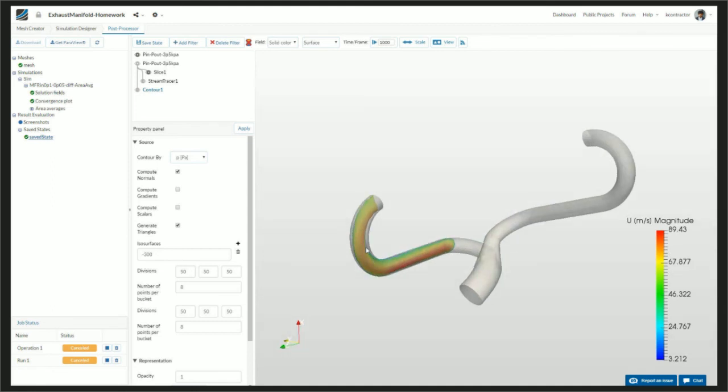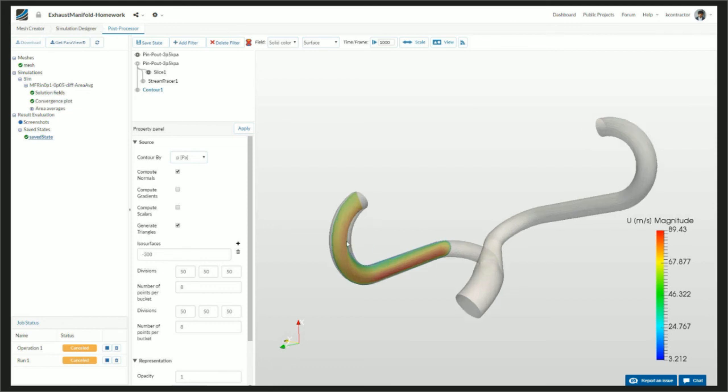Then again, it separates here in this region. The green region is where there's a separation zone, and this is what leads to some recirculation in the pipe. And basically, this slows down the flow a bit in that region. But you can see that it does not have a very huge separation zone. So this would not hinder the performance of our pipe in such a huge manner. And we can also look at the streamlines.